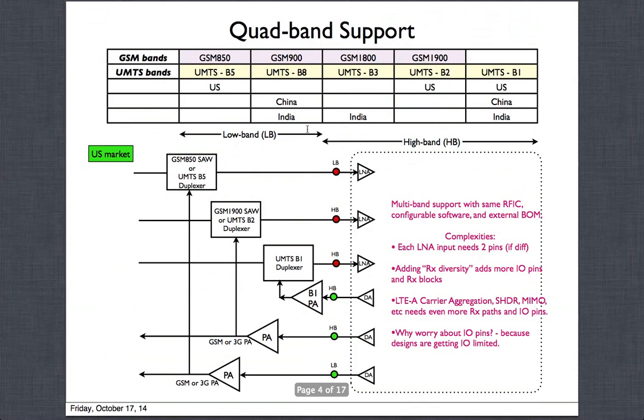Okay, so maybe I should just go back to this table and try to explain. So I could have a case, and a popular case is band 1, everybody uses it. This is where you could deploy LTE. Now when it comes to LTE-Advanced, and you are not able to get enough channels on this band, you might say, I have band 1, and I also have a different band, a lower band like this. Okay, could be say 850 or 900 megahertz.